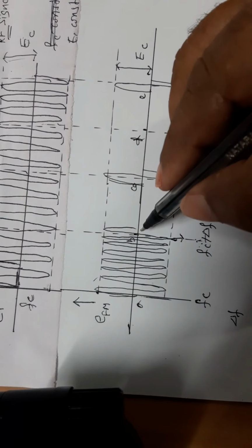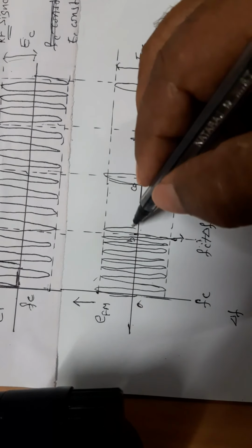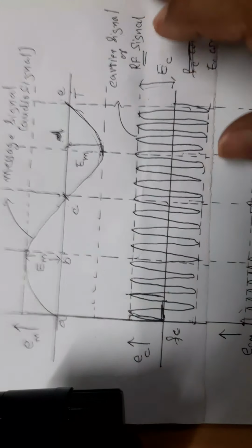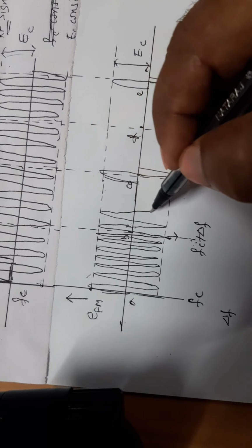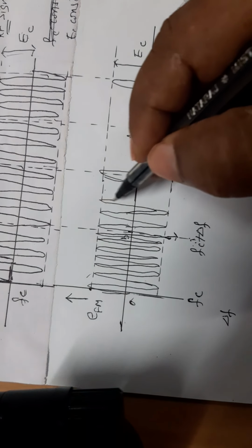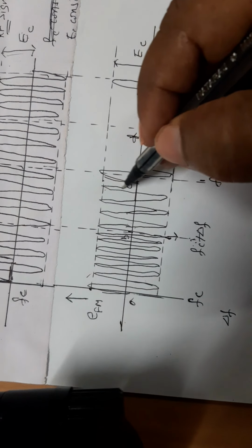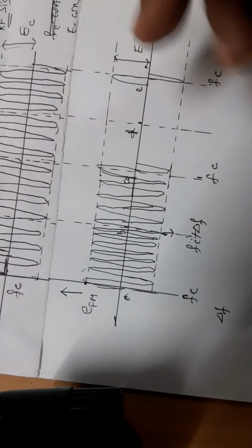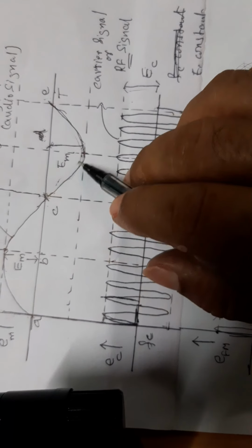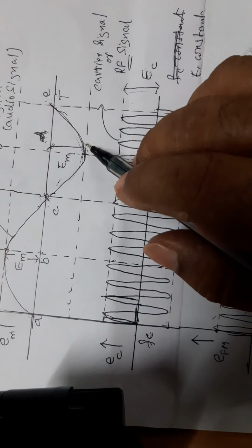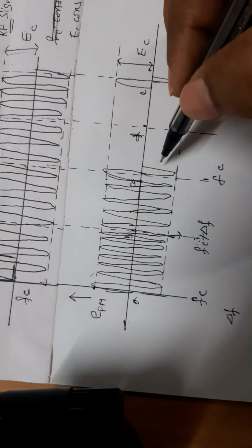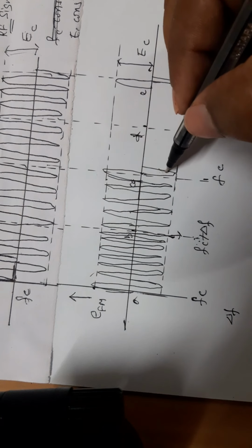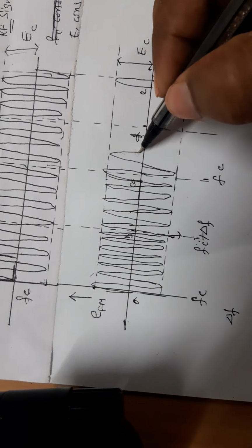Now, again the frequency reduces to its normal frequency Fc because the amplitude reduces. Now write that the period increases slowly to the period of the carrier signal. Now see, the amplitude decreases here and reaches the minimum value. Therefore, the resultant frequency should decrease. So I will write, since the frequency decreases, the period should increase. Therefore, I will write a larger period of the wave here.